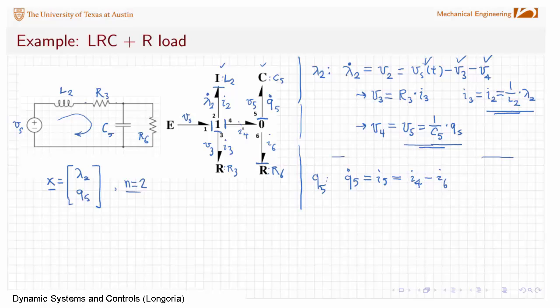Right, so what is I4? That's my first one here. How do I find I4? Well, I4 is the current here. Which bond is determining that I4? It's coming from that one junction. Which bond is determining the flow at this one junction? And that's I2. Remember, always come back to I2. Why? Because I2 can be expressed in terms of state. So I've got I4. How about I6?